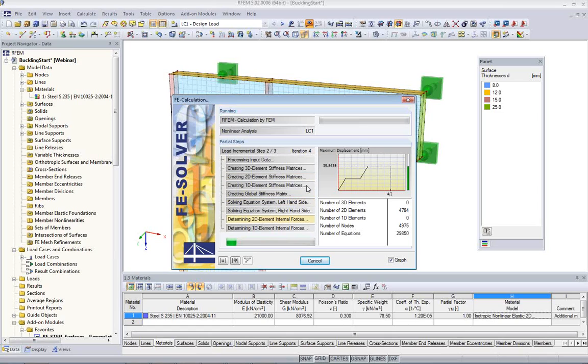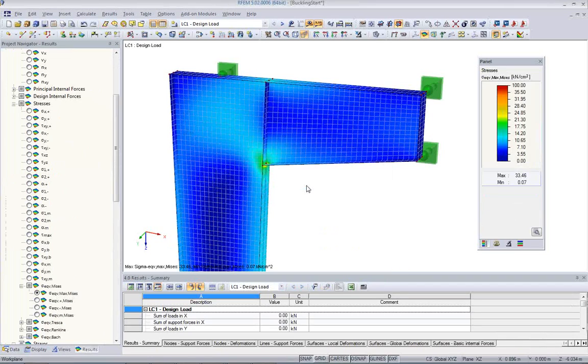It's also a good idea to work with load increments because you gradually load the structure and yielding starts gradually at the worst points and spreads from there. If you have a large yielding area and you apply the load in one step, it is sometimes called a shock for the structure, because there's a big change in the strength and in the stiffness of the structure, and it can lead to poor convergence during the calculations.